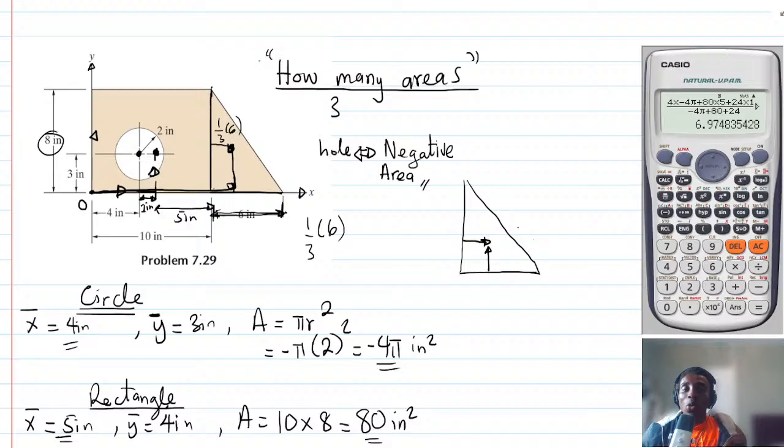So the question is, any side at all can be the base. It doesn't matter. The whole idea is that if I am standing at one side, which I'm calling the base, then the centroid will always try to act at 1/3 of the height in that direction. So if I call here my base, the height is 6.